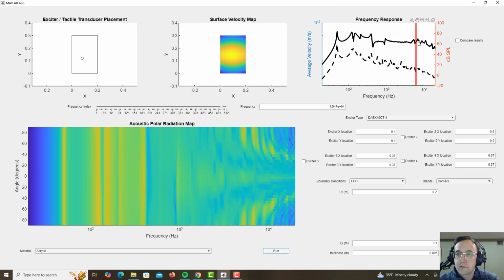All right, so we have our results. That's a pretty radically different frequency response now with the free panel and the corners unable to move. So let's look at some of these modes now. At 50 hertz, there's something going on, so let's try to find that. Yeah, that's this. That's where it looks like the whole middle of the panel is bending.